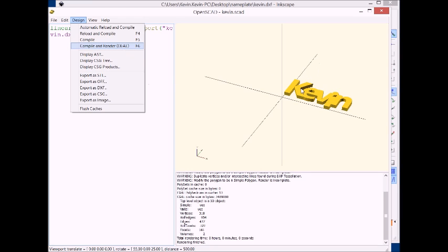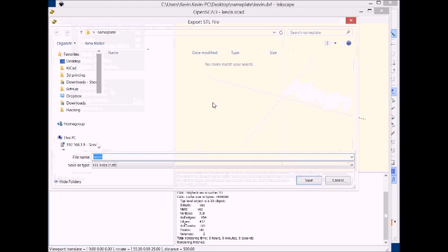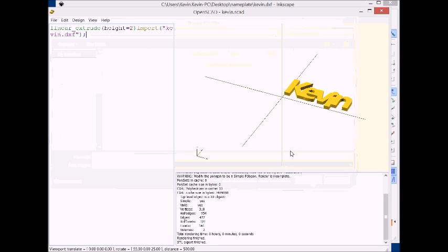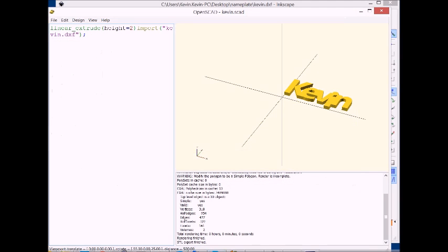And if nothing shows up or chunks show up, it means that you still have curves in your file, and so you need to make sure that you change all the segments to lines. Okay, so now we'll just export it as an STL, and I'm going to call it the same name again, and that gives us an STL that we can then import into our 3D printing software. For example, lately I've been using Cura.